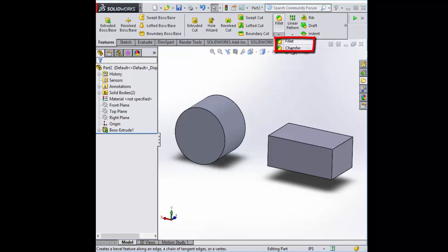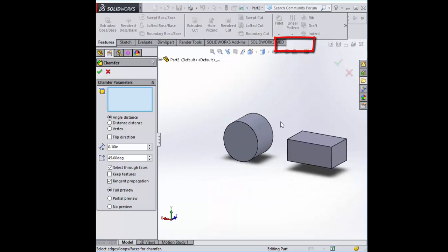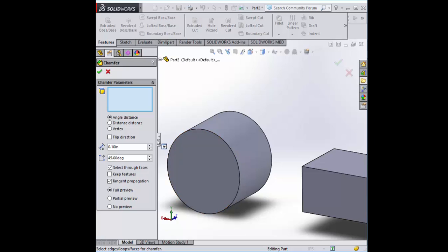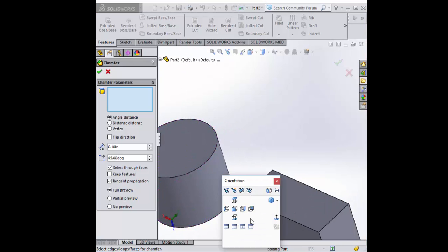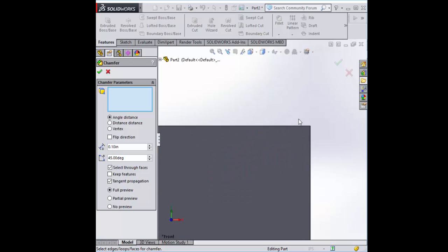Let's talk about a chamfer. A chamfer is sort of like a fillet. It blunts the corner, but instead of making it nice and round, it's just a simple diagonal cut. There are a couple ways to do this. You may have seen the chamfer dimensions in your worksheets already. This says 0.1 inches down at a 45-degree angle. Let's look at this.